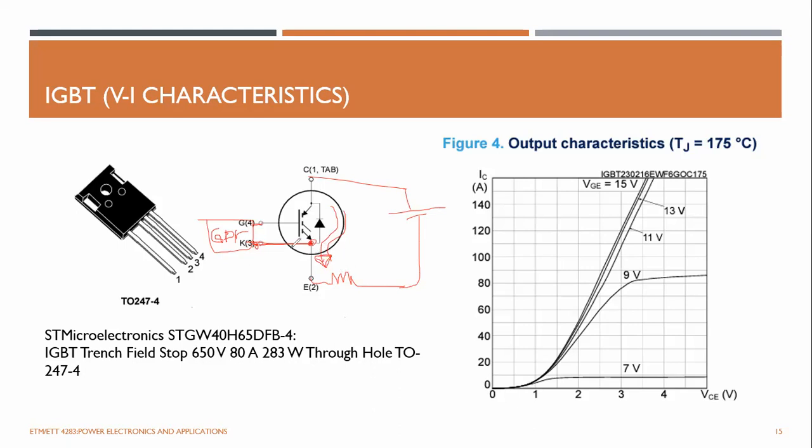And if you use the same pin for the gate driver, any small resistance across this pin, maybe 1 milliohm or something, then if 100 amperes goes through, there is a voltage drop in this pin, right? So your gate signal needs to compensate for that voltage drop. 1 milliohm times 100 amperes is 100 millivolts.